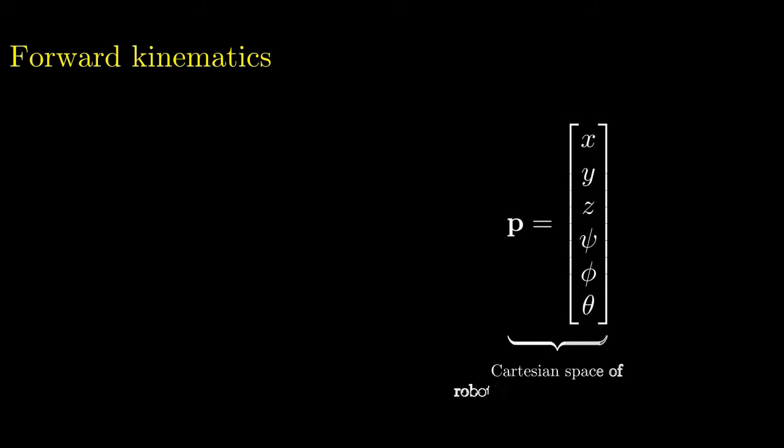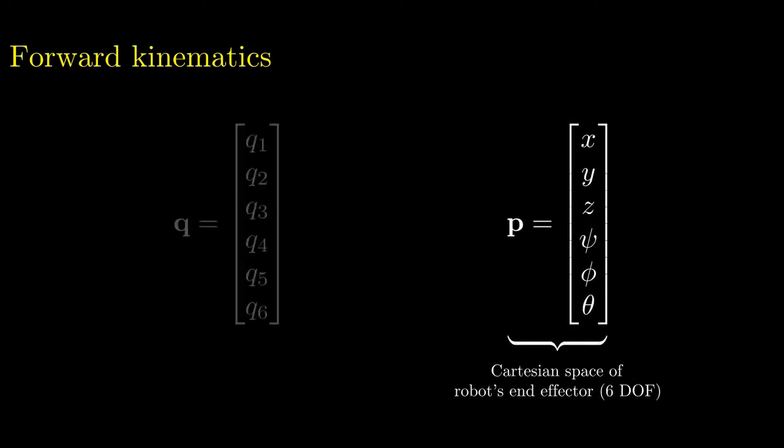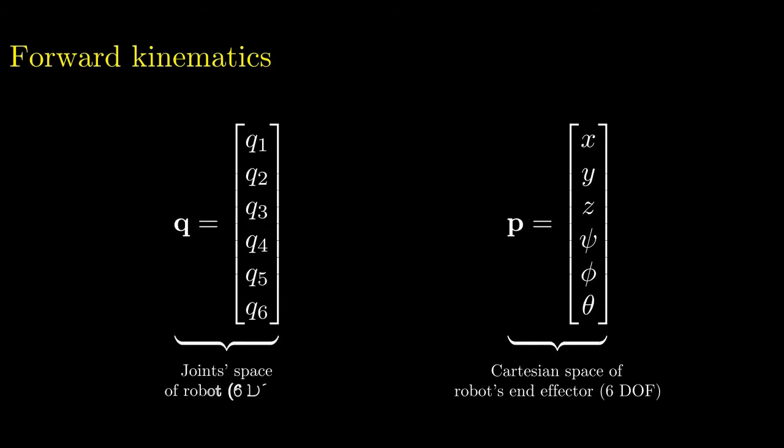Okay, forward kinematics has as its objective to determine the position and orientation of the robot's end effector, or the gripper, from the prior knowledge of the angular or prismatic displacement along each robot joint. Then, for the analyzed robot, it is required to know the pose of its end effector when each revolute joint is submitted to an angular displacement. It must be realized that this robot has 6 revolute or rotational joints to achieve a kinematic behavior of 6 degrees of freedom at the end effector.